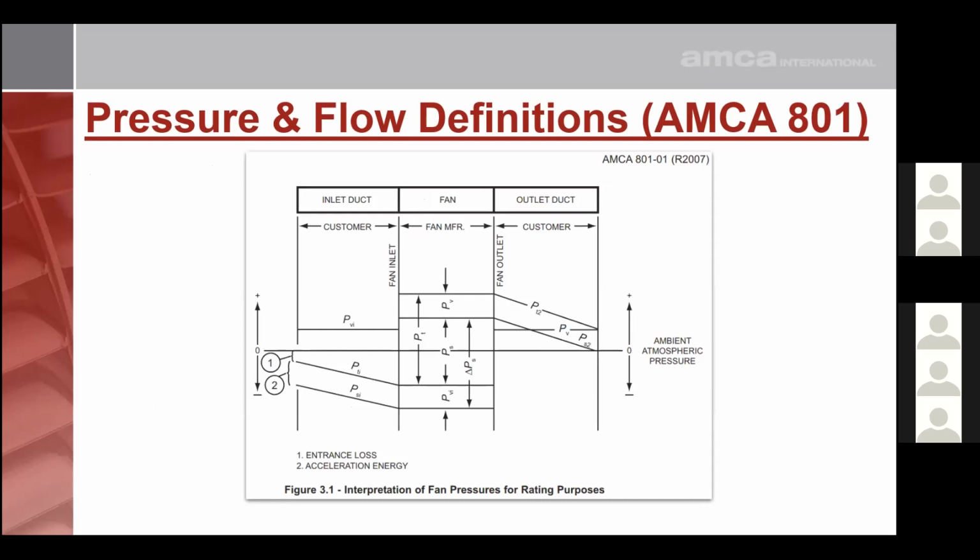Here's a quick outline of what the different pressure points are at the fan inlet and the fan outlet. You can see graphically how the different pressures can be listed and how they can also give a different total value, and so it can affect fan sizing.